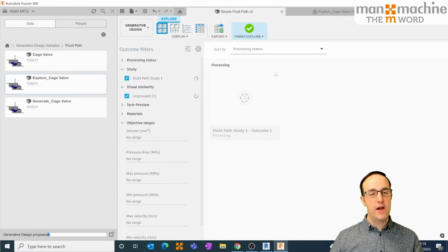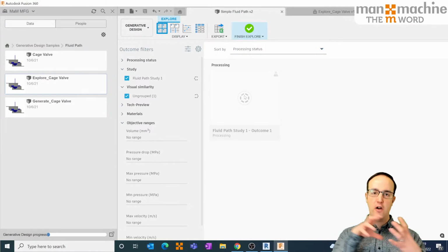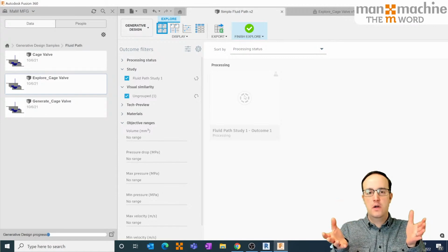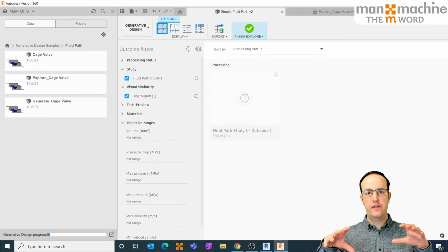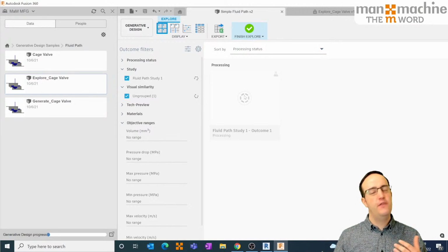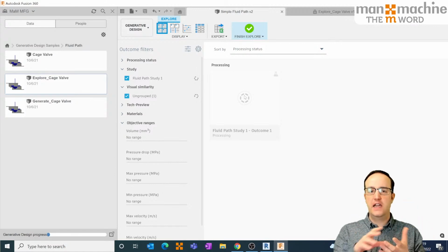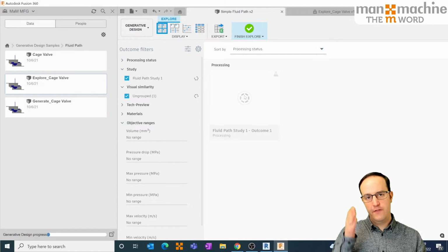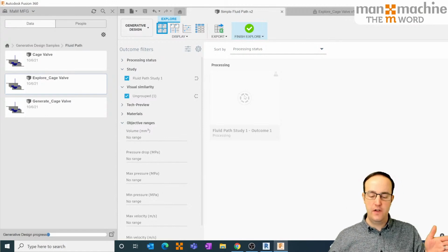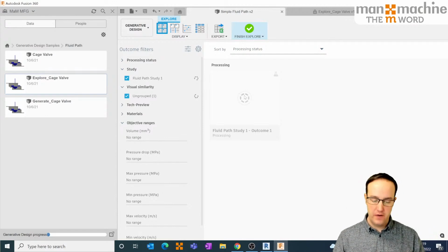But the key really is how you start it. So if you've already got a design, you create a volumetric model of the inside. Just cap either end with the patch tool and create those boundary conditions, and then use something like Stitch. If you were going from Inventor, you could use Sculpt to create a sculpt of the outside design and the two patches. That gives you your starting fluid. You then have a shape at the start and a shape at the end for your inlet and your outlet, and then you can start the process as we go through.